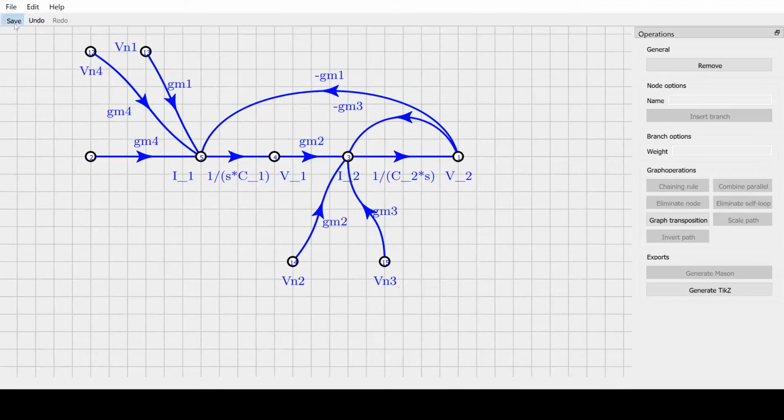So I see that I basically have two ways how the noise can go to the output. Not four, only two, because VN1 and VN4 are different inputs and they have different GMs going to the output, but they will have the same structure, just the component values will be different.